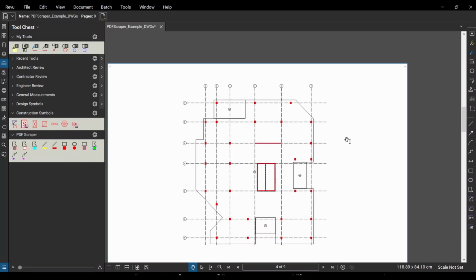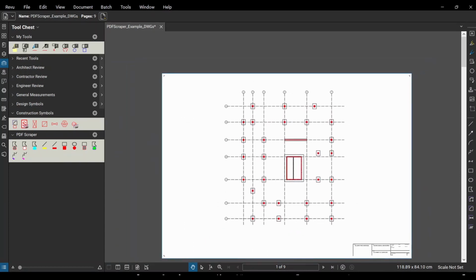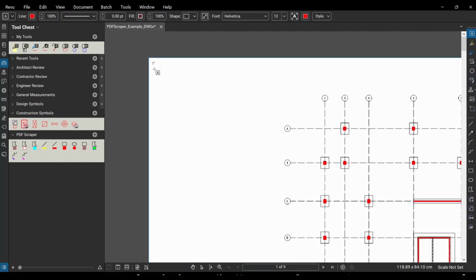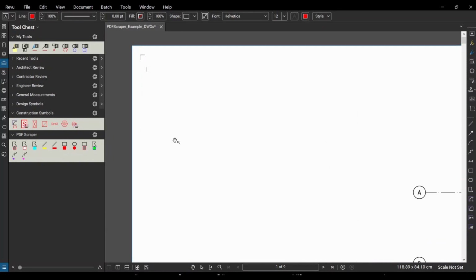The one final thing that we should add is the level heights and the names of each of the levels. So all I'm going to do for that is add a text box somewhere. This markup can be anything. There's no requirements on what it is. But what we're going to say is name equals, let's say, footing.